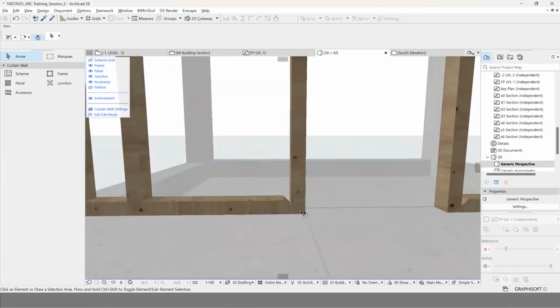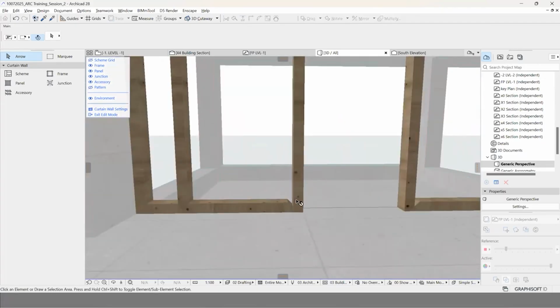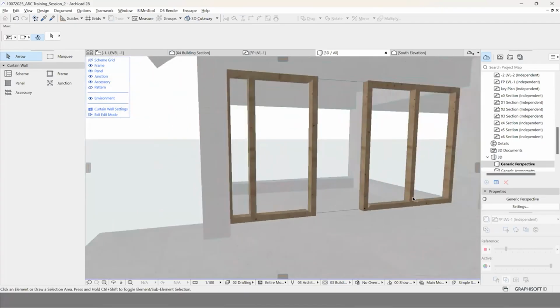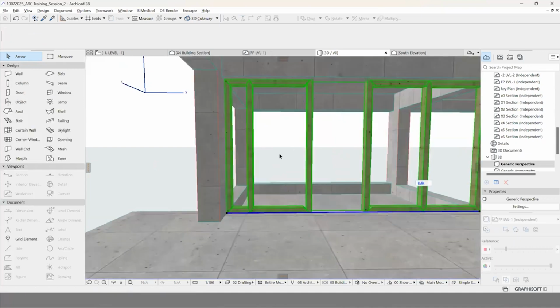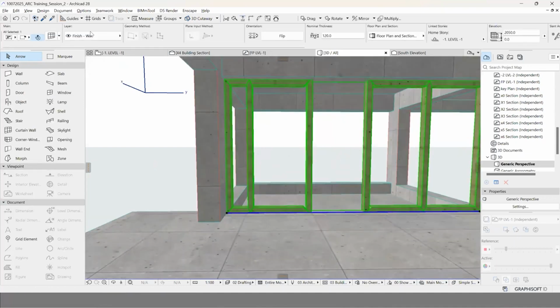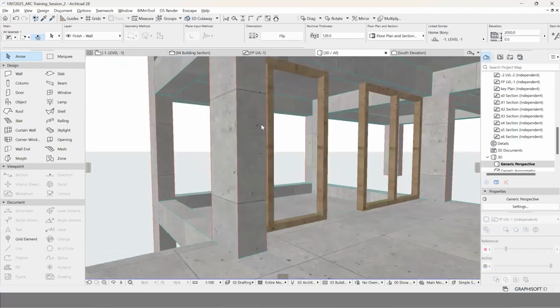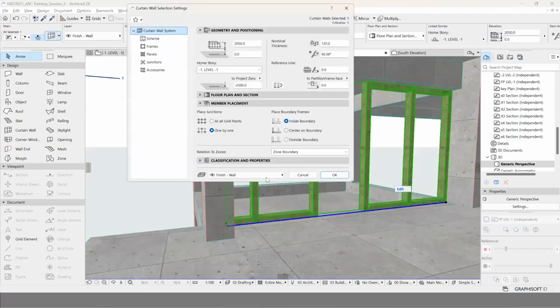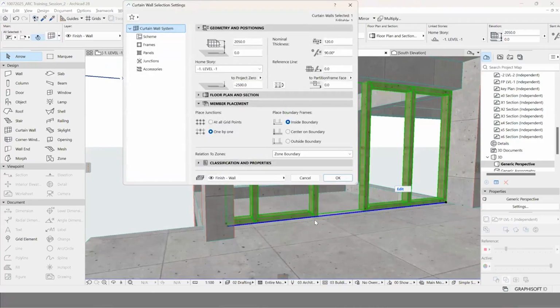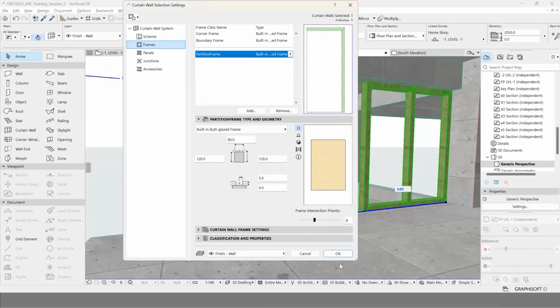There are also a couple of things like these errors you might see. This can be addressed, which I will be showcasing to you. Those are actually based on a concept called priority. But mainly that way you can just delete these elements altogether and make sure they're plain. Even though I deleted, there's still one single element overall outside. And that particular issue can be addressed by just changing the intersection priority. That is a property here. By increasing or reducing them, you will be able to change the property.